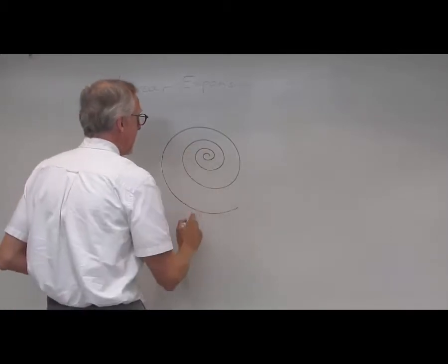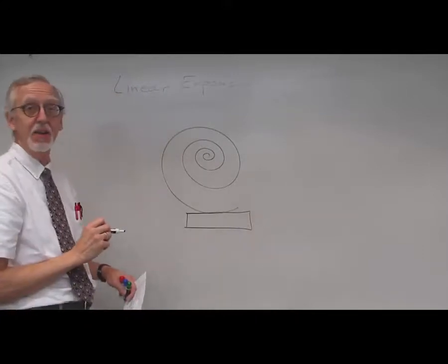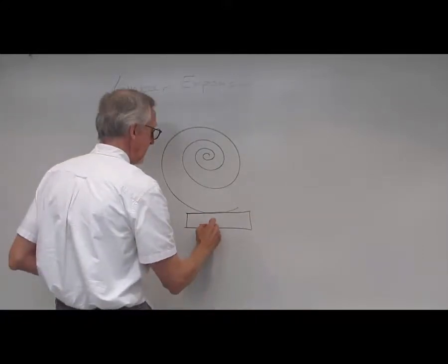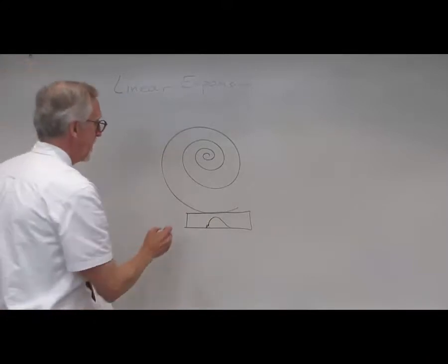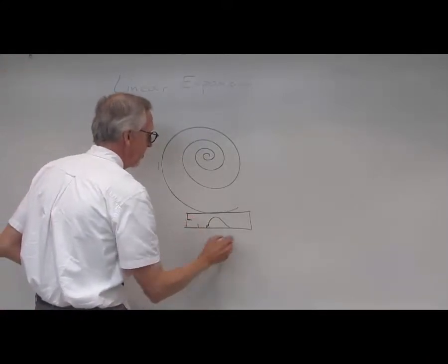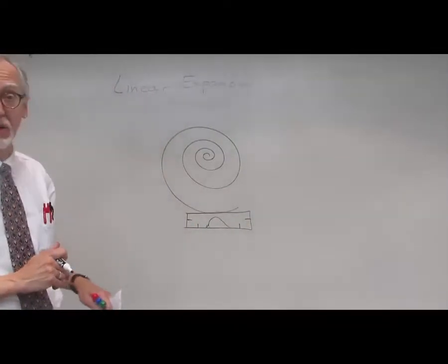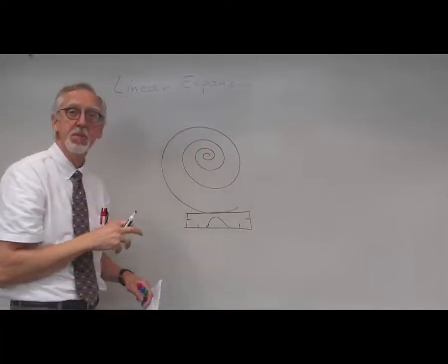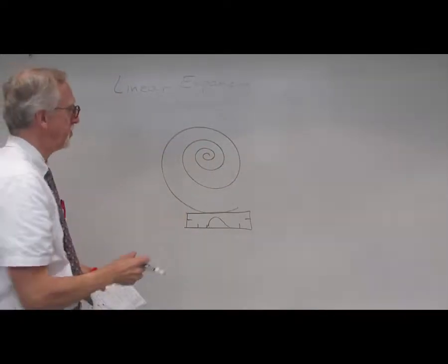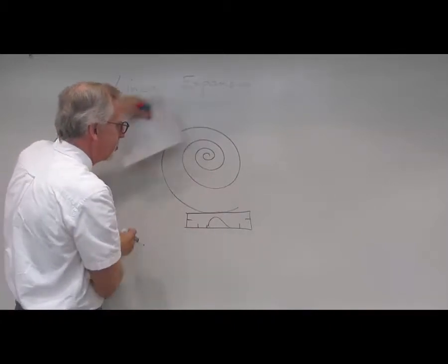You'd have a bimetallic strip, and on the bottom of the strip would be attached a little vial with some mercury in it, a little lump of liquid mercury. Then at one end of the strip would be 2 electrodes, and at the other end, 2 other electrodes. Now, when the coil, say, warmed up, it would expand and move this way.